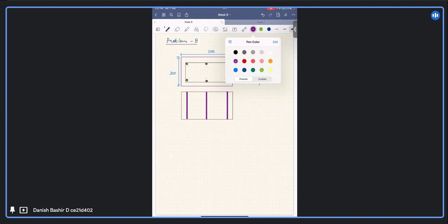Our load will be having load capacity Pu, Pu corresponding to the balanced section Pub. And it will be having moment carrying capacity Mub corresponding to the balanced section. I'm writing the subscript x as well because the bending is only along the x-axis, Pubx and Mubx. So if I do all the calculations regarding these 25 diameter bars and 8 diameter ties, and my section side is 500.